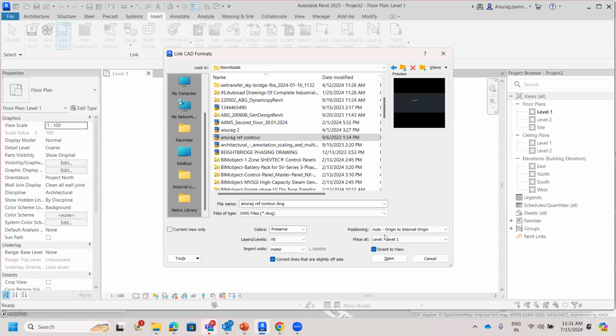So it becomes sometimes very difficult to get that file back once it has been loaded onto Revit. Initially it becomes very difficult to catch that file again, even by zooming to an extent where you have to see that file, but you are not able to see it. So this is the common thing that happens. Whenever you insert a particular file, after inserting you need to bring that file onto 0 0 at the Revit interface. Otherwise, you are not going to work a long way back from 0 0 to somewhere else onto the other latitude and longitude coordinates, X and Y axis.